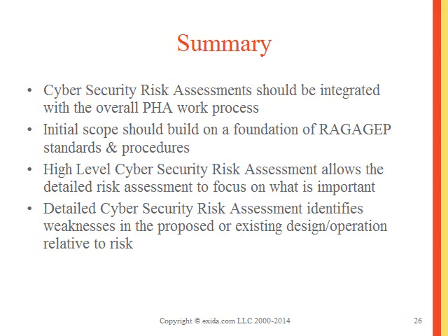Okay, so there's a question that says, do field devices that are smart, for example HART-enabled, pose additional threats to a safety instrumented system? Do you recommend against smart devices in SIS applications? Well, the problem with extending your field bus to HART, Profibus, Modbus, any of those kinds of devices is you open up a new port for potential threats. So depending on what your architecture is, or perhaps the security associated with the actual installation, yes, this could be a problem.